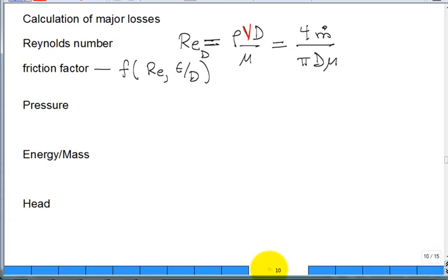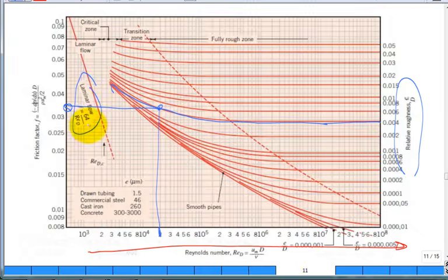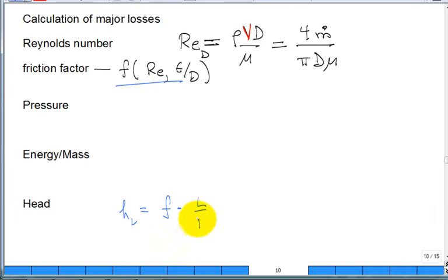So now I could calculate this h_L. How would we do it? Friction factor, just know how to calculate. Go to the Moody diagram if it's turbulent flow. If it's laminar flow, that's easy, 64 over Reynolds number. That's also on here. There's your laminar flow, and there's your 64 over the Reynolds number. Then you have the length over the diameter, and then that velocity head, V squared divided by 2g, and that's how you would calculate it, wouldn't you? Okay.